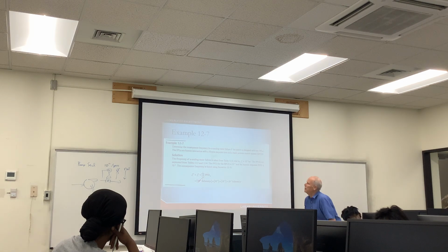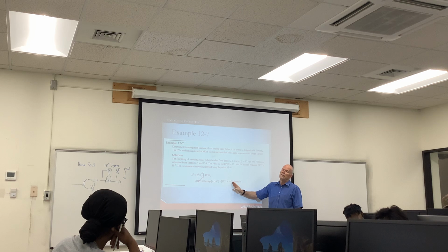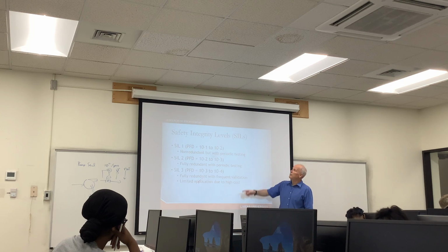Because you would multiply the probability of failures with the demand of your mitigation system. You came up with 10 to the minus 3. Now let's say you needed 10 to the minus 5. You need to multiply by 10 to the minus 2, don't you? Well, where do you get the 10 to the minus 2? You get it from a CO2 system.